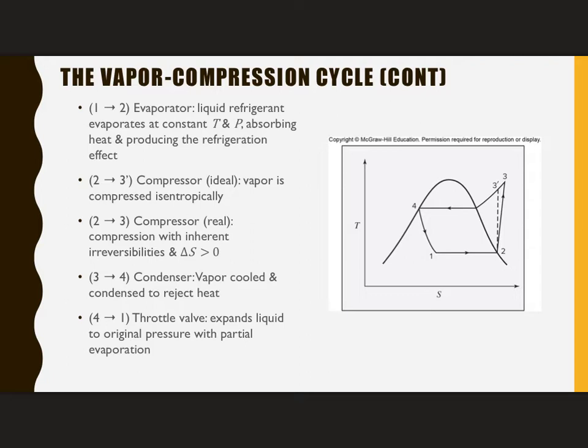So let's go over these steps. So the first step was that evaporator. The evaporator is the part that is taking the heat out of your cool substance. It's going to operate at that low temperature, T sub C, okay? And what's happening is heat's coming from this cold material, and it's going to cause a liquid to evaporate. It's going to be essentially a constant temperature and pressure process, and that heat is going to make it have more energy that we're going to then need to dissipate.